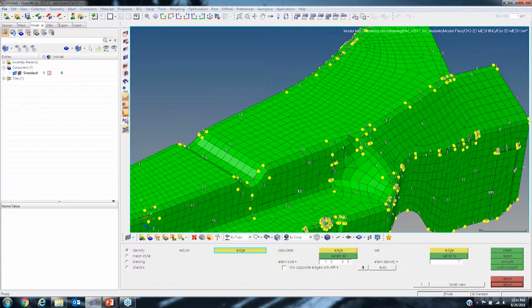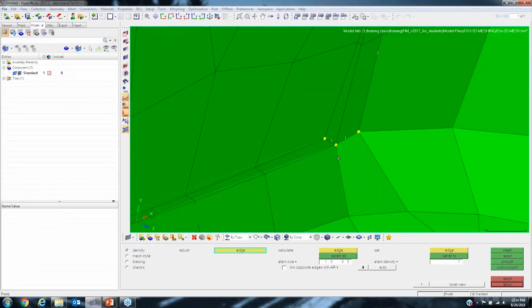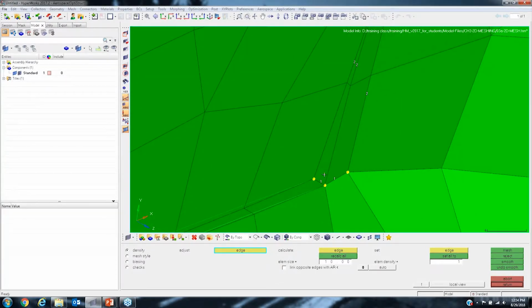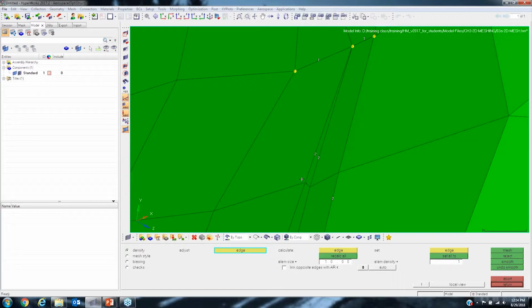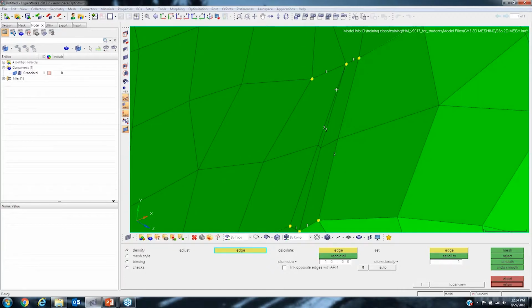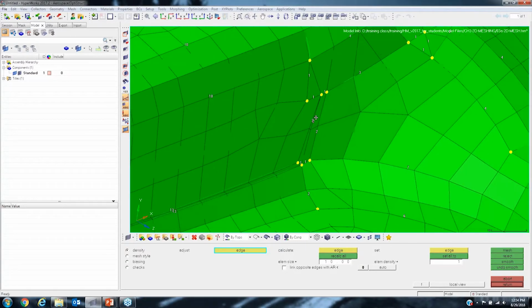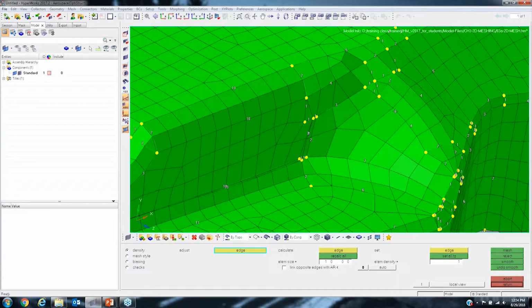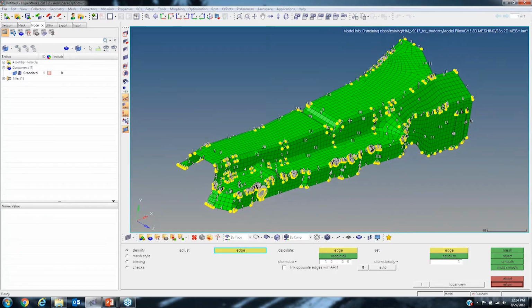But the thing is, the main thing that you want to watch out for when you're generating a 2D mesh is these kinds of cases here, where, for example, you have these very warped elements, like this triangular element that you have here. Hopefully you guys can see that, where it's extremely warped. So any results that you get from that type of element are going to be horrible results. You're going to get an incredible amount of stress focused in that region, and it's just going to give you bad results. So ideally, what you want to do is you would want to clean up this geometry, right?